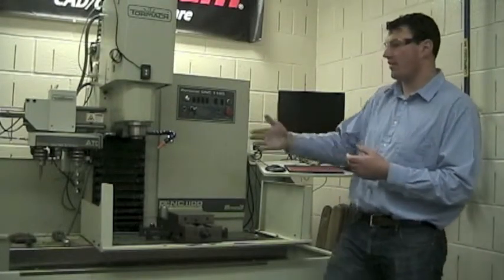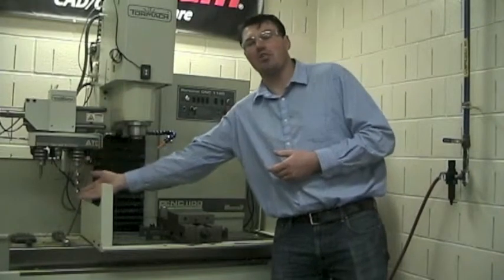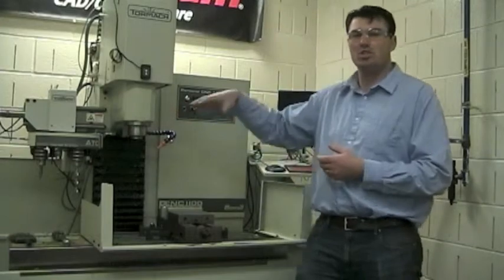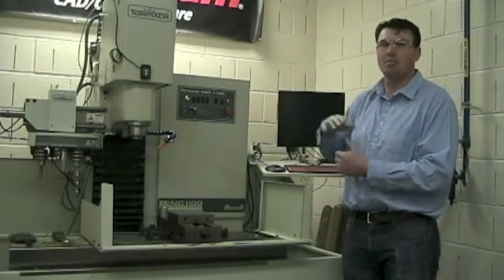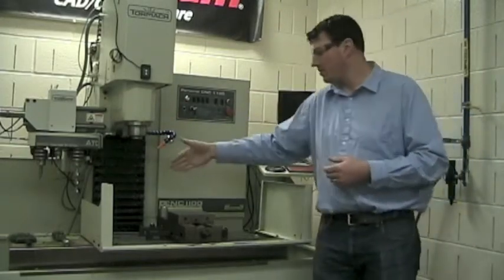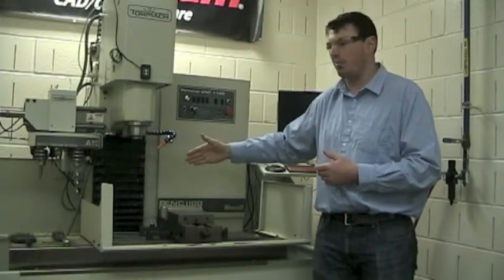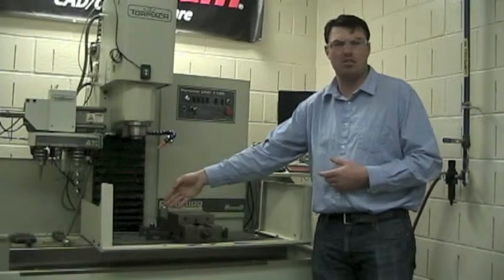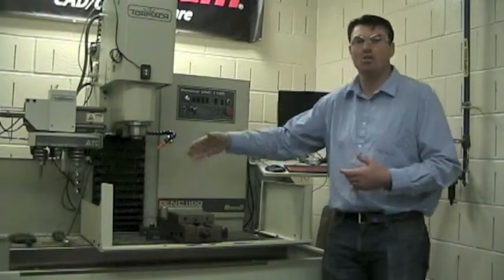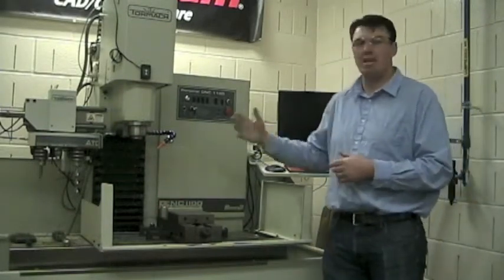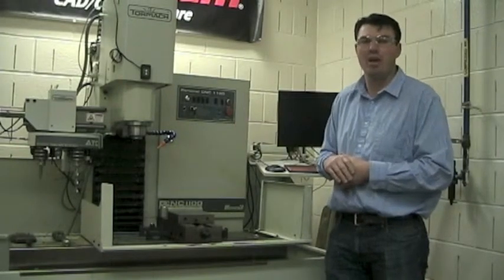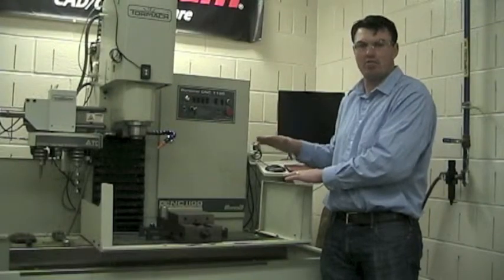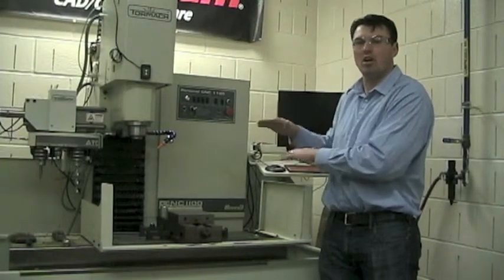For example, we could have a very, very large drill chuck with a long drill bit in it, or a very, very short end mill. And if the machine does not know the difference in height between those two tools, we could either be machining air up above the part, or in a much worse case, be bringing this tool over into the vise or into the bed of the machine, causing a tool crash, possibly damaging the machine or damaging the tool. Either way, we want the machine to keep track of the heights of the various tools and adjust accordingly during the program run.